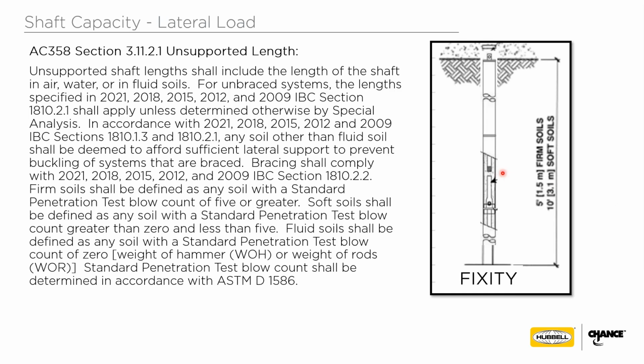When we look at elevation of structures, we have to look at the pile in the sense of what we're trying to do as an element, a compression element. It's going to be resisting, obviously, axial compressive forces, perhaps some tension or uplift, and also, in some cases, considerable lateral forces. So we have to deal with unsupported length, and we also have to deal with soil types with respect to how deep or how embedded these piles have to be in terms of achieving fixity.